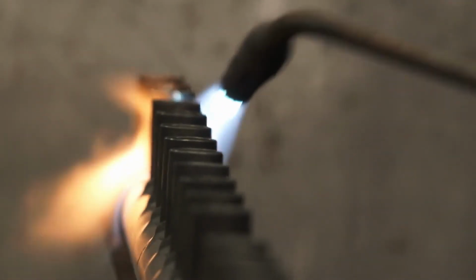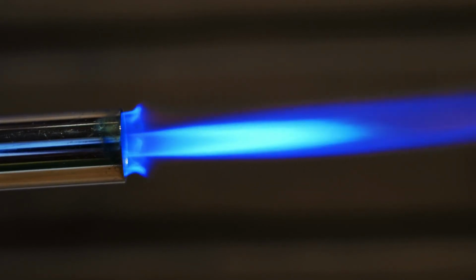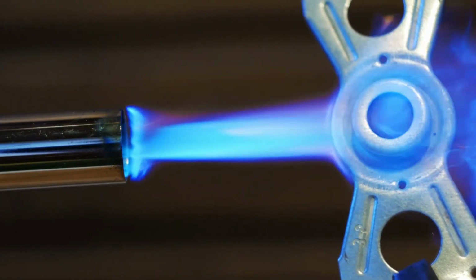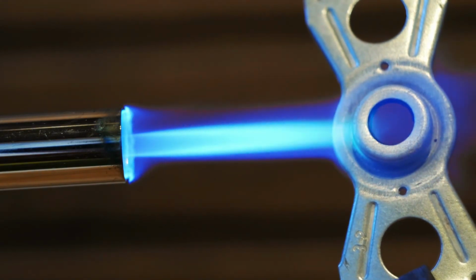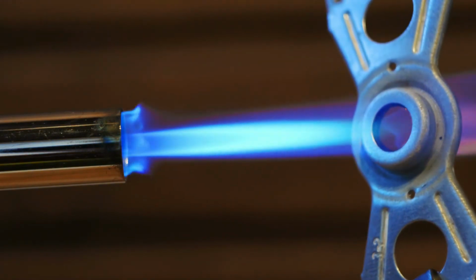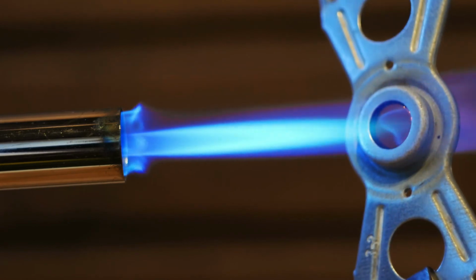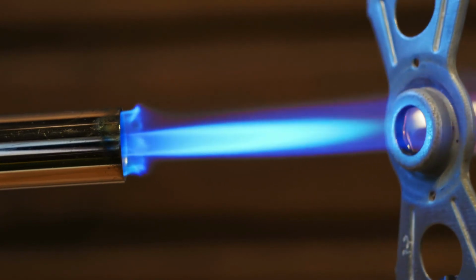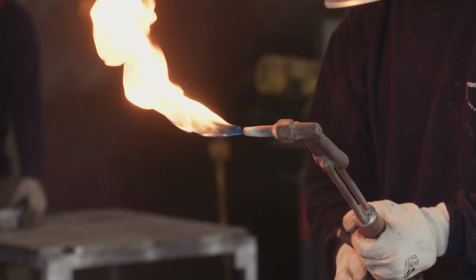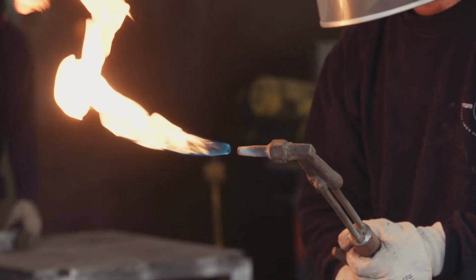Backhand welding is a notable technique where a carburizing flame is used. We would recommend the welders to use this flame on a metal whose carbon content is already high or metals that are hard-faced such as nickel, zinc or Monel. One thing to keep in mind while using this flame is that it is not a good flame for soft solder operations, and its outer core should be used for solder processes as we need low temperature in it.